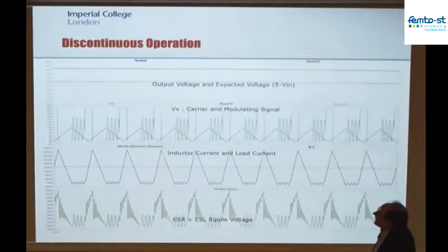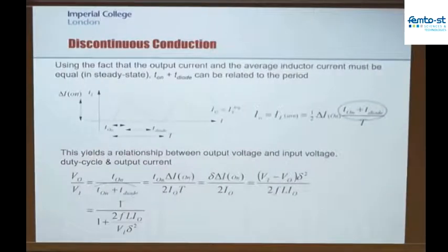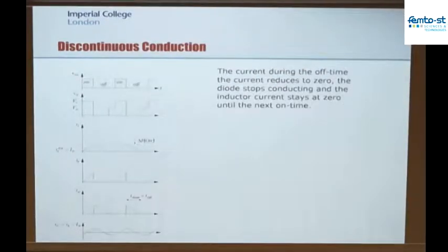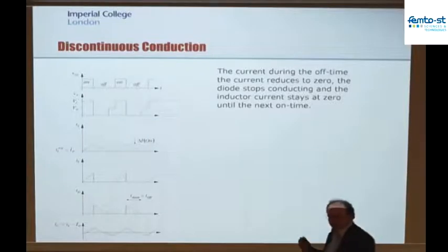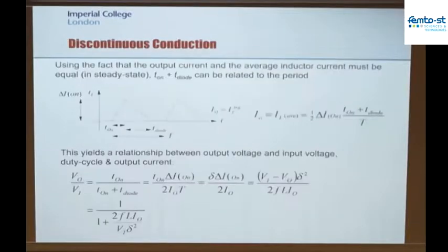When we looked at the behavior of this circuit here, these are the kind of idealized graphs, and we're comparing these to what we see on these simulations. We expected the voltage node Vx to go from Vin when the transistor's on, down to 0 when the transistor's off and the diode is conducting, up to Vout when the current in the inductor drops to 0 as part of this discontinuous mode of operation, and then back up to Vin when the transistor turns on again.